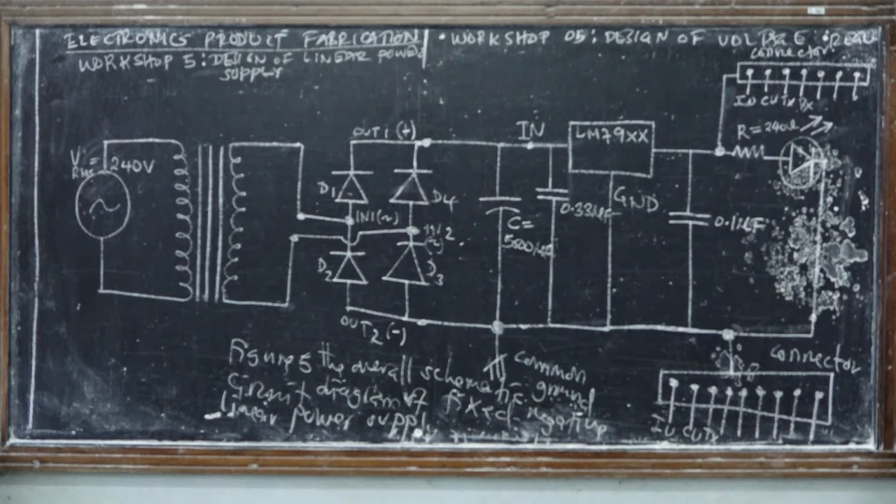Are we together? Whenever you encounter that challenge, and you will encounter it if you are designing electronic systems, especially if you integrate your system with a communication unit, for example a transmitter and receiver. The transmitter will consume a large amount of power to propagate the information to the media. So if you use a single linear power supply of, let's say, positive 5 volts or 12 volts, it will not be able to power the whole system.